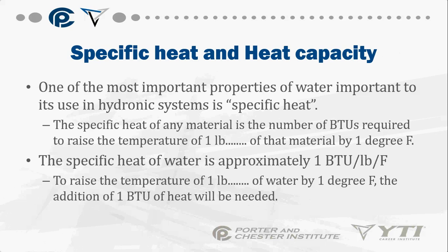Which is why you have an aquastat on a boiler. An aquastat is what controls the temperature of the boiler. We don't want it to get so astronomically high that we can create a dangerous situation. We only want the boiler to get so hot, and we only want it to get so cold, so that we don't have to constantly add and remove heat at such a great amount.